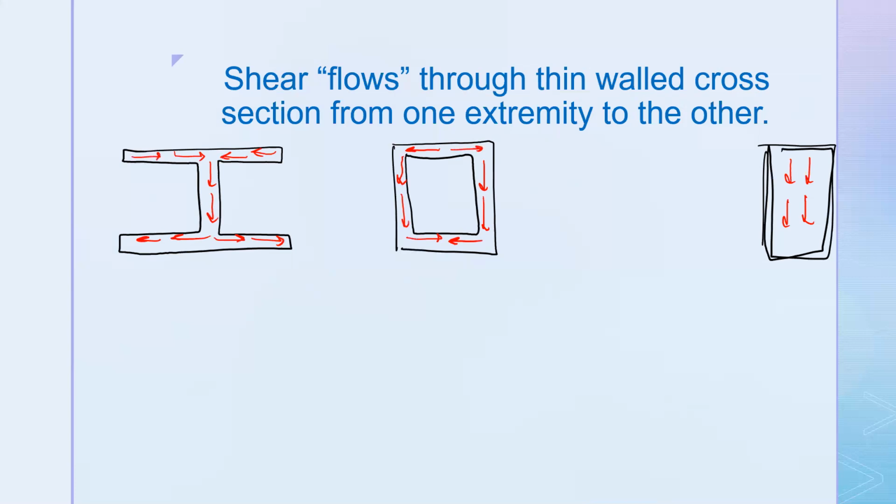And we can show that this is the case by taking a series of cuts. So remember how we initially showed that we had shear stress by taking a section cut that was, say, horizontal, and we had the normal stress acting on the cross-section on one side, and then a normal stress acting on the other side of that cross-section that were not equal and opposite because the moment was changing, therefore the normal stress was changing.